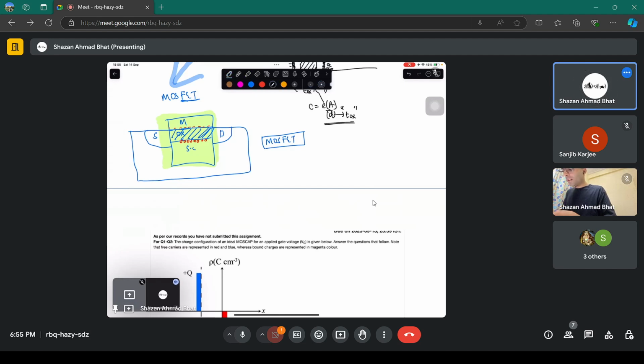Then you connect this to some particular voltage, let's say negative voltage. You connect it to the substrate also. You ground everything. You connect this to a particular positive voltage source. You ground it also. Then you give your signal at this particular terminal, which is the gate voltage. This is the circuit of the MOSFET.